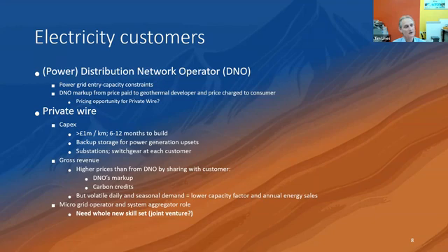Electricity, in some ways, is simpler, because very often your first port of call is a distribution network operator or a grid operator. But the problem around Europe, you'll find when you try to do this, is that most grids are not designed to take large amounts of input from somewhere they've not done so before. Most countries that have offshore wind have known this all along: all of a sudden they've got to restructure the grid so that it can take power not from a centralized coal-fired power station, but from an offshore wind farm. And certainly in our experience, we find exactly the same thing, where we're looking to embed generation close to cities, and we say we've got, I don't know, 15 or 20 megawatts electric to put to a customer, and the grid says, well, we don't have any capacity for you. We might have it in 2035, but we don't have it now.